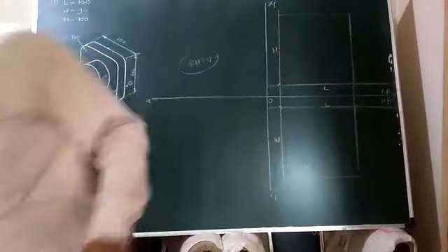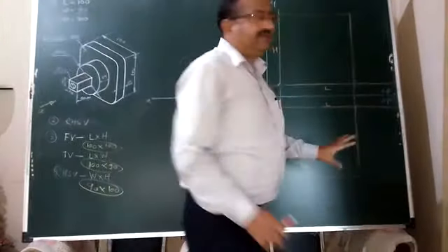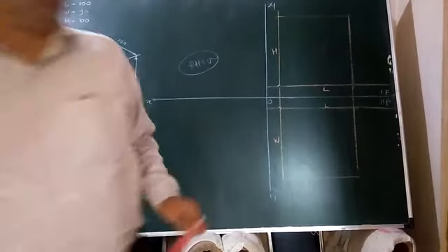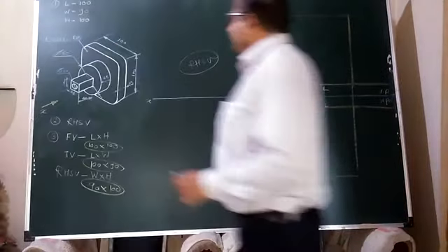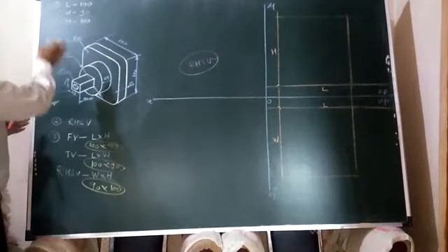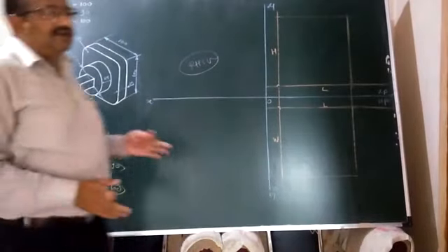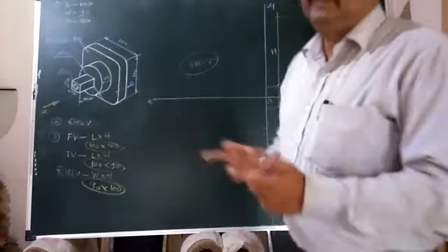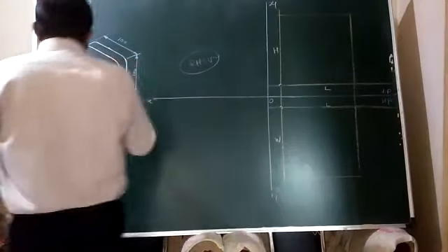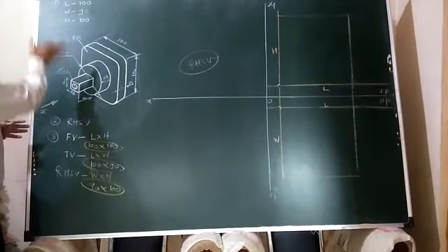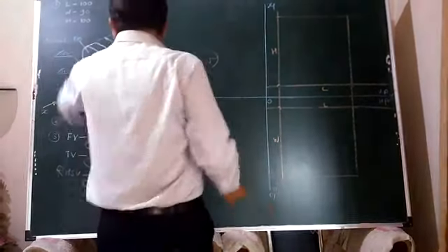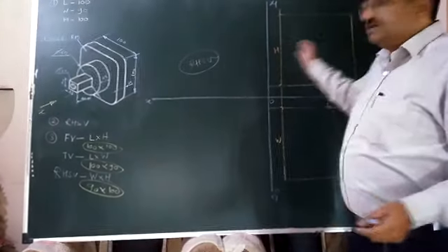Now the very next step, immediately, both the areas are ready for us. We should construct the line of symmetry in all the views. Line of symmetry. In the front view, just see, horizontally as well as vertically, we can cut. A line of symmetry is nothing but when we cut that object through that line, it should be converted into two identical halves. Okay. So in the front view, just see here, when we cut in this way or in this way, it will be converted into two identical halves. So two lines of symmetry, or central lines, we can construct in the front view.